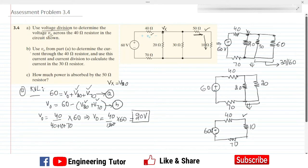So this is the answer of question 3.4a. Now in part B we are asked to find the current flowing through this 40 ohm resistor by using the value V0 we have found, and then use this current and current division to calculate the current in the 30 ohm resistor, which is this one. We have to find this current, which is, let's say, I0, and then from it we have to find this value, which is I30. So let me calculate it here.